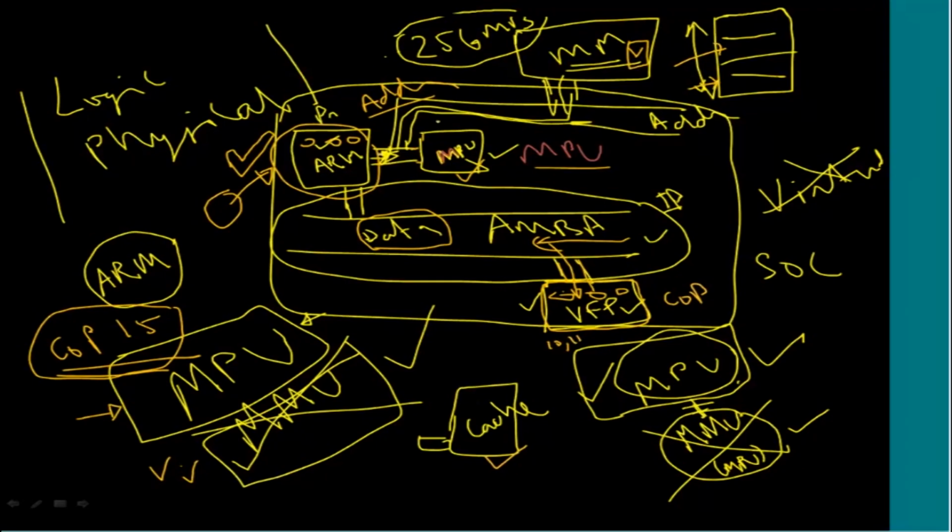But the generated addresses can be seen by the MPU or for that matter MMU, and then they can read it and do some translation, and the circuitry can be such that the MMU will translate the address and be connected to main memory. In this case, the same address bus goes to main memory, but MPU also looks at the addresses.